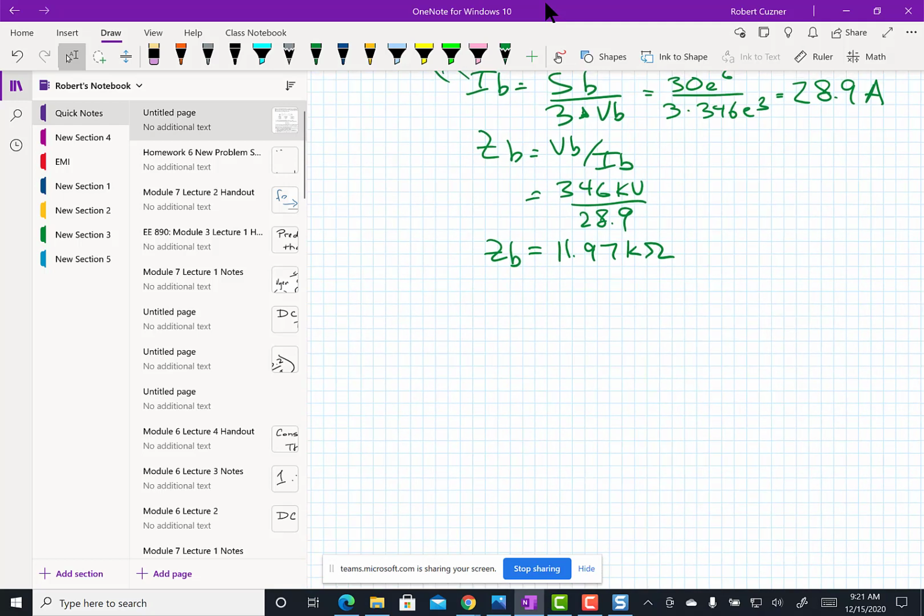So if you're going to reference everything, you're going to reference everything to the transmission line. Now, here's where a lot of people go wrong. You try to use turns ratio. So you try to do it the way we did it in chapter 2 with the single phase transformer. Turns ratios, you will get it wrong, I guarantee.